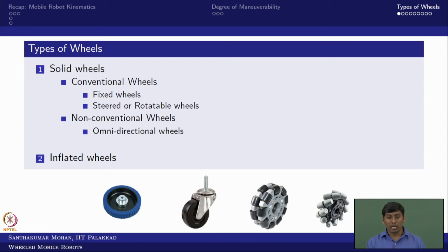So now we come to the other case. The omnidirectional wheel means the passive roller would be perpendicular to the hub axis. So now this would provide least resistance in the lateral direction, but the wheel hub actually rotates and would be moving only in the longitudinal direction. Whenever there is a resistance or some force in the lateral direction, it can slide. That is the difference. Whereas the Mecanum wheel, it is not that way.